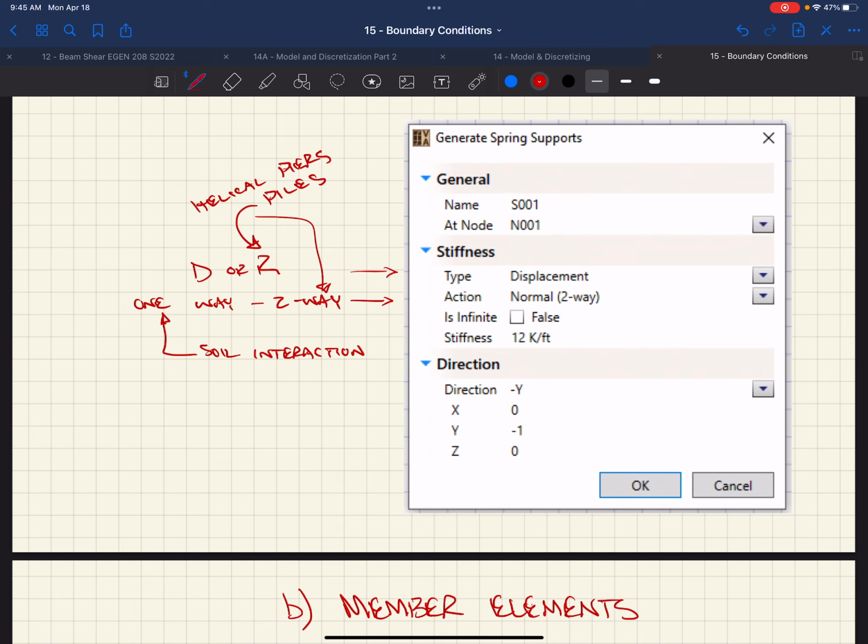Yes. Do you find that the helical piers are governed more by lateral versus like the allowable that you have to do when you're setting them up? It depends. Because they don't give you a lot of language usually on the lateral, like, well, you just batter. Soil specific. Well, you batter the pile, right? So, like, instead of putting the pile straight down, you can drill the pile at like a 45-degree angle, right? So you still get the same load characteristics of that pile. You're actually loading the pile in and out, but that obviously has a component in the lateral direction.